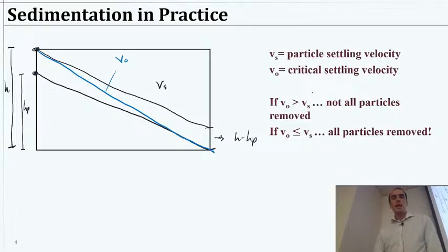So imagine, again, the bowling ball if you have any confusion. Compare the bowling ball particle to a slower particle. If you design a swimming pool such that it should remove certain particles with some flow going through it, well, that's kind of overkill for a bowling ball. Bowling ball will hit the ground in a very short amount of time. So you could be flowing a lot of water through there and still settle out that bowling ball. So keep that in mind. When we make a comparison, we will compare between Vs and V naught.